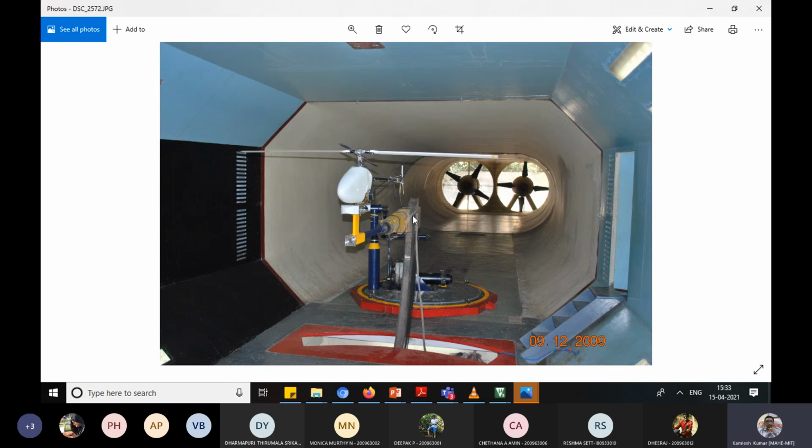But what you can do, these systems can go inside, so this can change. What happens is this will make the angle of attack. If your wind direction is not changing, the wind direction will be the same, and only you are orienting the direction of the aircraft, the nose direction of the aircraft. So this becomes a reference, like your reference wind direction is the same, but this direction changes. So that is called angle of attack there.